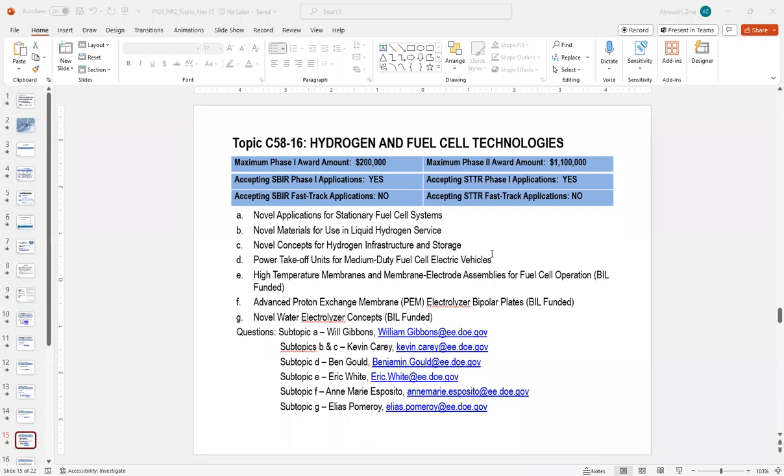In some cases, we're also looking at the ability to dispense as much as 10 kilograms of hydrogen per minute. And in high pressure storage, we could look at pressures where we could easily see 20 bar, or if it's a high pressure filling station, as high as 700 bar. Low cost and the ability to perform well under these conditions is critical. And also looking at applications where you will undergo numerous or large pressure cycles. So you will be working at very low pressures and low temperatures to high pressures and relatively higher temperatures.